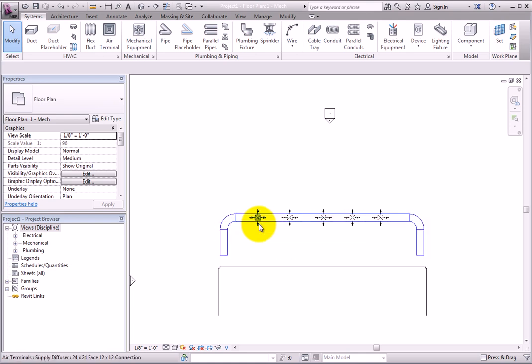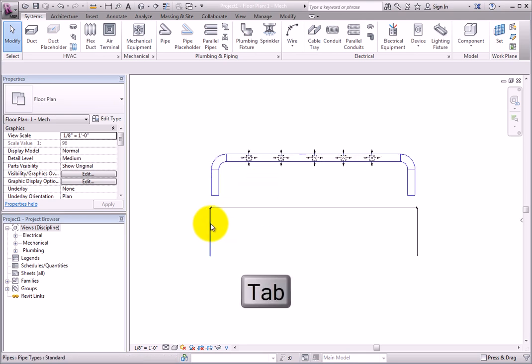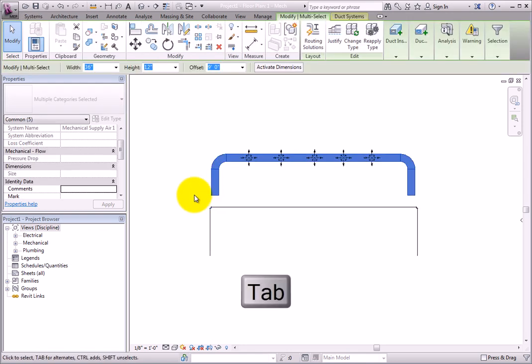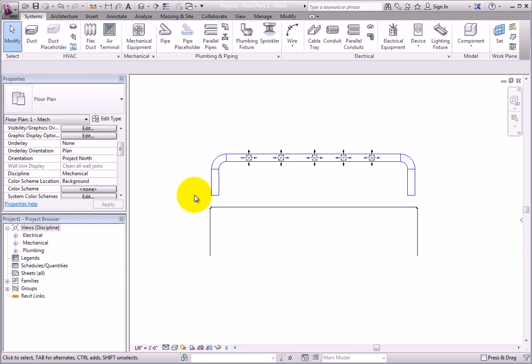When you want to select a series of connected pipes or lines, you can Tab to cycle the selection of a chain of pipes or lines. You can also press the Tab key to select a face or center line when placing dimensions. And when snapping to points on existing elements or components, you can press the Tab key to cycle between different available snaps. To cycle in reverse order, hold down the Shift key while pressing the Tab key.